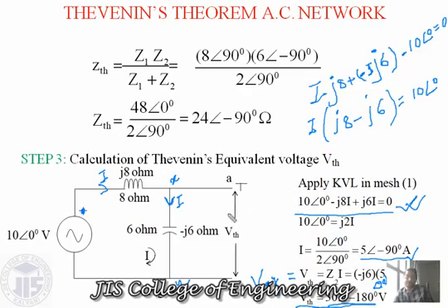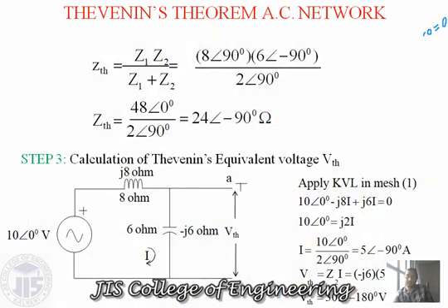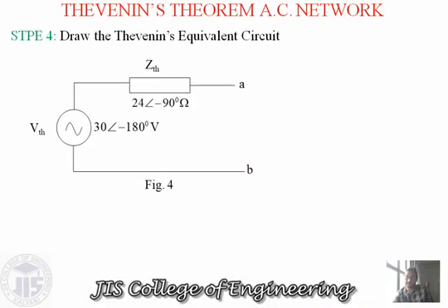So already we have found the Thevenin impedance ZTH, and here we have found VTH. Now what will be our equivalent circuit? Our equivalent circuit must have VTH in series with ZTH and in series with ZL. So let us go for the circuit design. In series with VTH and ZTH there will be the load resistance RL, or load impedance, whatever we can say.